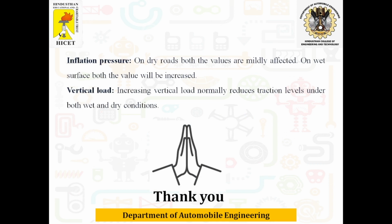And inflation pressure. On dry roads, both the values are mildly affected. On wet surface, both the values will be increased. And the last one, vertical load. Increasing vertical load normally reduces traction levels under both wet and dry conditions.